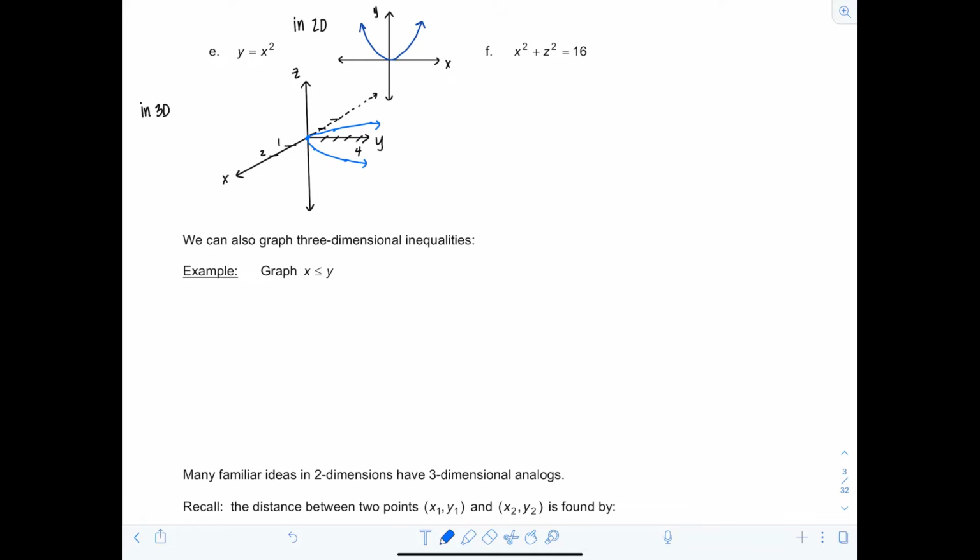Just in the XY plane. And then what you need to do is project this graph parallel to the z-axis. So the best way to do it is you just pick some arbitrary distance, okay? Say I'm gonna project it maybe this much, okay? And then I'm just gonna copy that distance and attach it at various points on the graph.